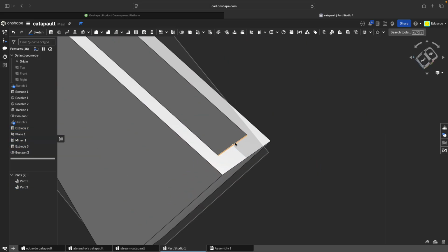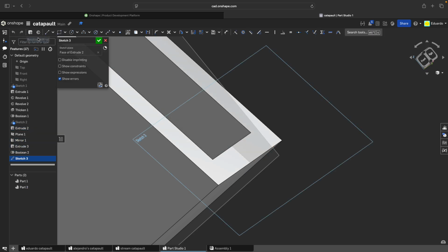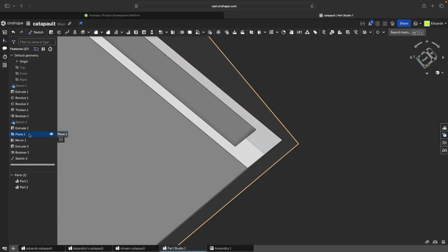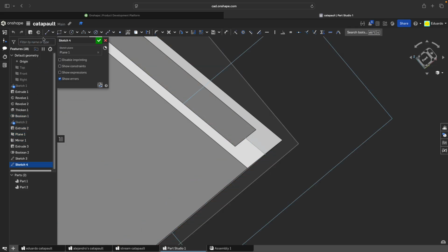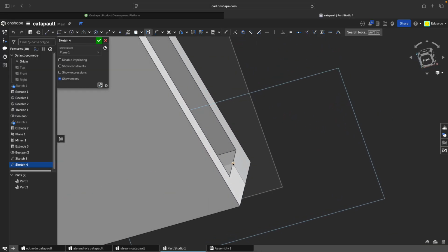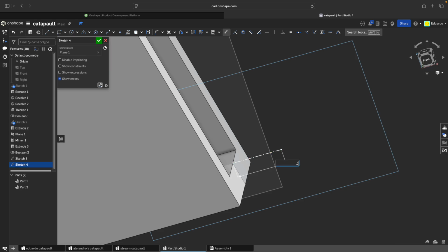So we have one more sketch left. Actually two more. So let's make a sketch here. This can honestly just be a line. So hover over this, wait till it's a yellow square, and then go to the other yellow square. You're good. And then on plane one, I want you to draw another sketch. So I make another construction line, and make this 0.2 inch.